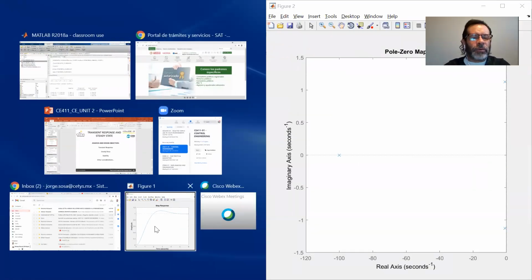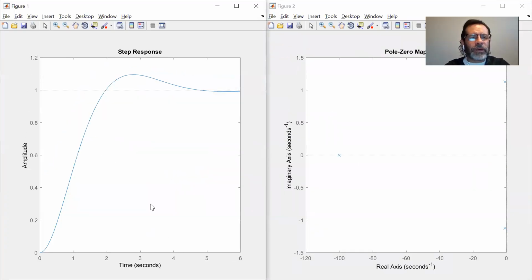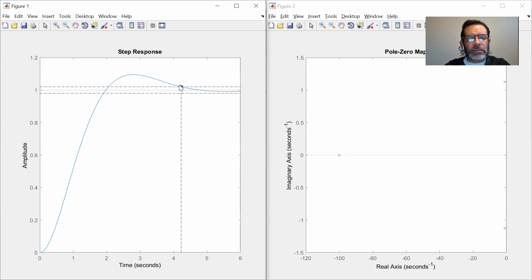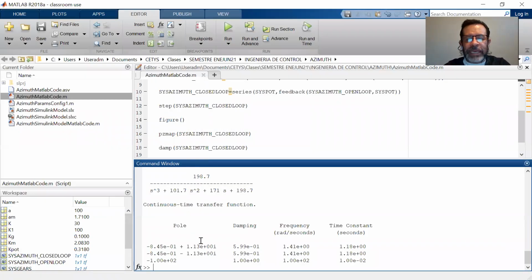Oh, another thing that we forgot to mention, well, look at this. Now we've got a smoother response with a lower settling time. The settling time is around the range, but we have less overshoot, less than 20%. What damping ratio do we have? We have very close to 0.6, okay? So we're getting to a better value.